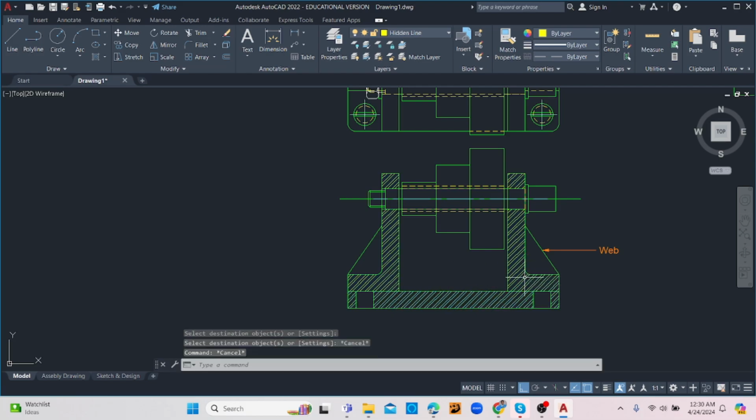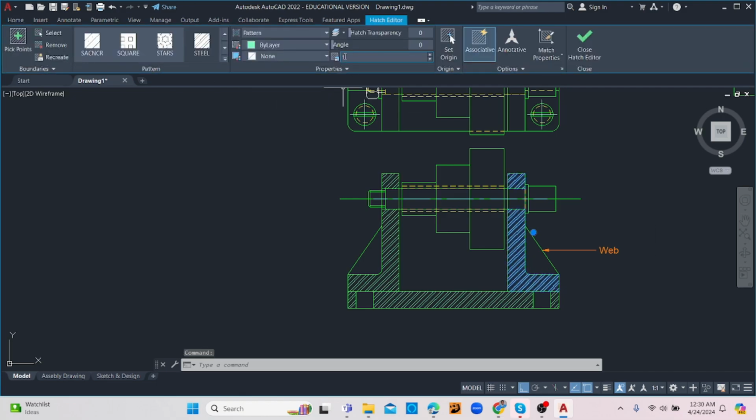They say anytime you have two different objects meeting together and that you're hatching them, you should change the direction of the hatch to indicate different materials or different parts coming together. So what do we do? We grab onto this here and we're simply going to be rotating it 45 degrees, or whatever it might work out to be. Alright, let's not use that one there. 45, no, let's rotate it 90 degrees. Alright, that's good enough. It's going to be the same on the other end as well.